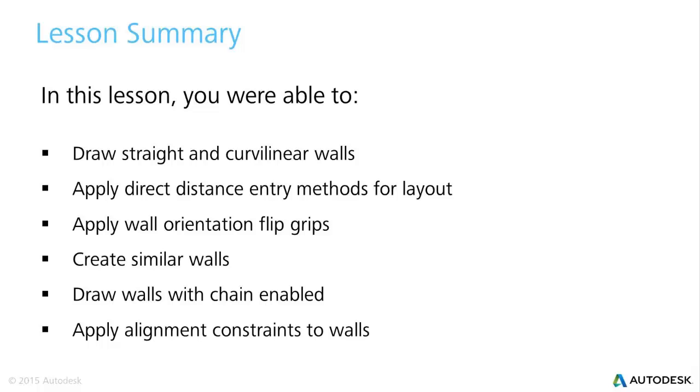We were able to draw continuous walls with the chain function enabled. And then we were able to lock in design intent by applying an alignment constraint to get two disjoined walls in the same plane to behave as one.